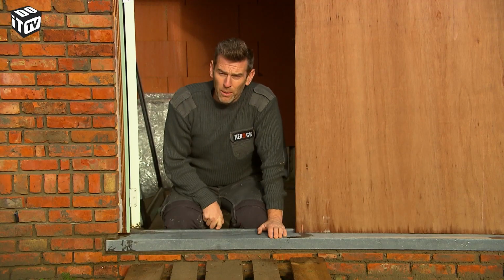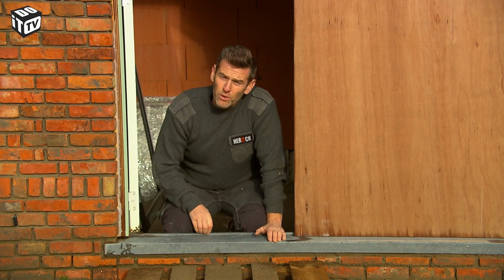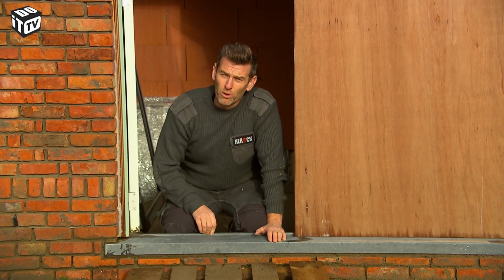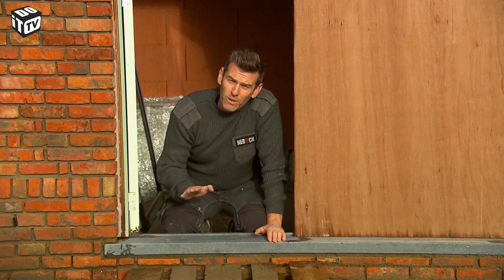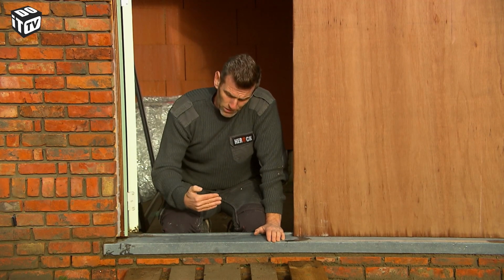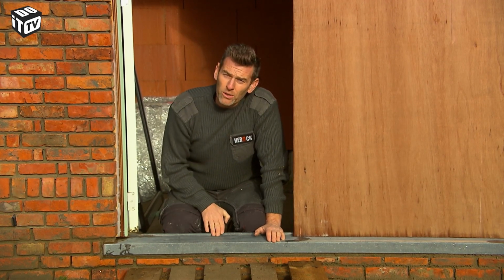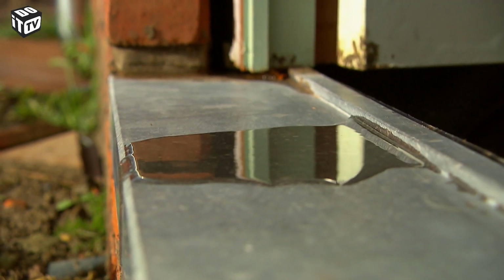Installing doors involves different thresholds. A threshold with an upstand. The threshold is also placed a bit further inside, and the draft brush under the door fits perfectly on top of the upstand. This ensures that when you close the door, the brush goes down and everything is windproof. Even when the door is closed and the rainwater is running down, it will come up against the threshold, causing it to run outwards and not be able to go inside.